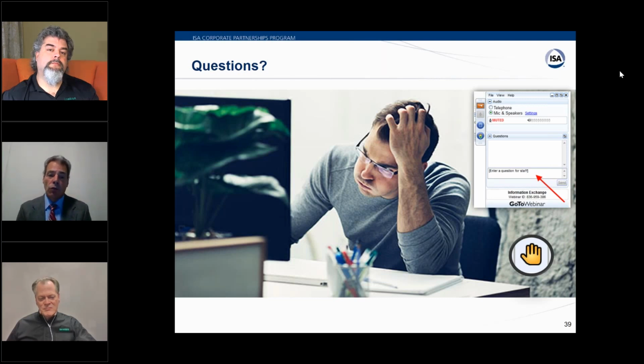There is a technical report from the ISA 96 Committee on Valves that is an entire technical report on partial stroking and the different methods of doing partial stroking and the different levels of automatic diagnostic coverage you'll get. Some of the very simple methods, you may only get like about a 30% diagnostic coverage factor. Some of the much more detailed and automatic and more frequent methods, you can get it up to about 80%. So it's going to be in that range.